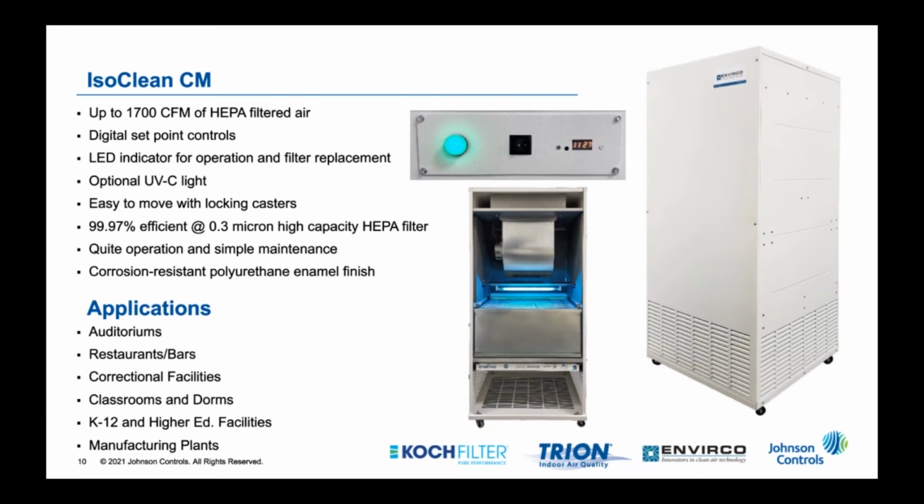So you will adjust the set point of the unit here from 1 to 100% of its airflow capability. Think about it this way, with 1% being equal to 300 CFM and 100% being equal to 1700. It's pretty much a linear adjustment from 1 to 100.